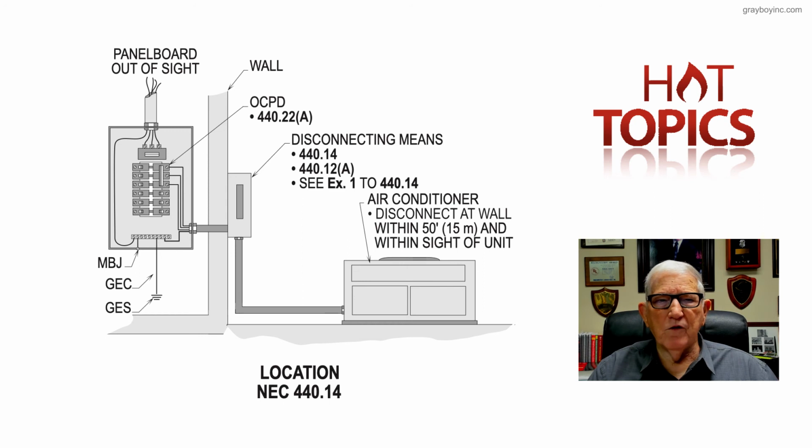But again, notice from the service equipment inside, we have the overcurrent device, and of course you know that would be sized to allow the unit to start and run by 440.22(A) of the code. And you have your conduit run to the disconnect and to either, say, a permanently installed type connection with conduit, or maybe flexible cable, weatherproof type cable that we would use.